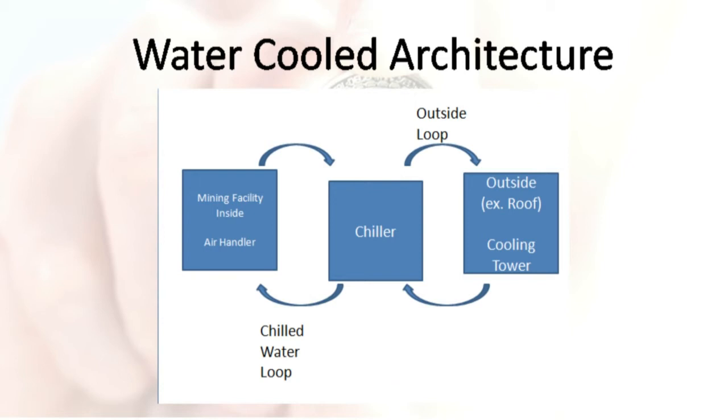In comparison to using an air conditioner in the air-cooled architecture, the cooling unit in this architecture is usually an air handler instead. They have the same general function, however. They do it quite differently. The cooled water in an air handler is moved through a coil, and to get the heat withdrawn, the cooled water is heated and then pumped back to the chiller. As in what you see in front of you right now, the chiller is just a heat exchanger of the facility and external refrigerant loop where the main goal is to transfer the heat to the air outside.